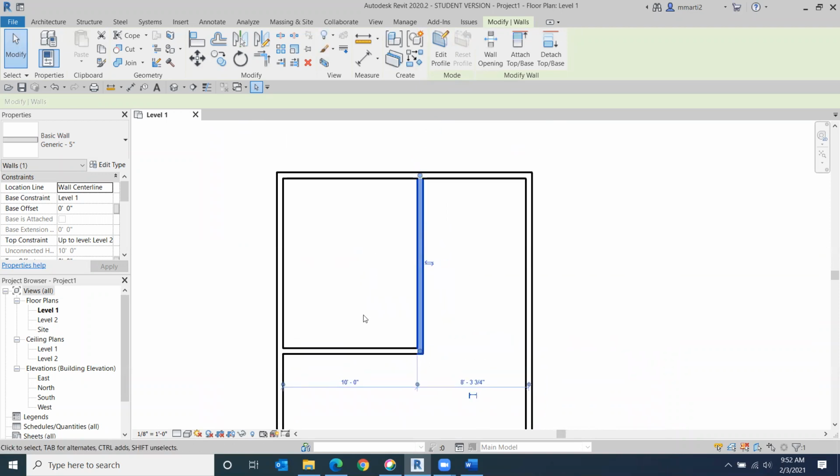Now we can lock our internal walls as well, but I recommend you lay out all your internal walls before you start locking internal walls, just because things are going to be off a little bit, and that we're aware of, because we don't know the actual thickness of your external walls. It can throw off the measurements of your internal walls. Just get these as close as possible, and then we can talk about that on Monday. The important thing is to know how to adjust these so you can get these as correct as possible.